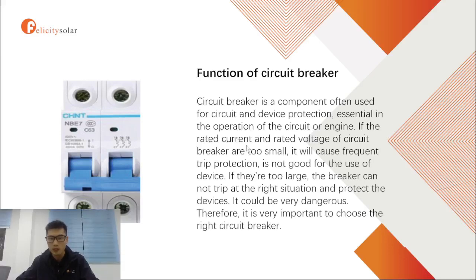If the rated current and the rated voltage of the circuit breaker are too small, it will cause frequent trips, and it's not good for the use of the device. And if they are too large, the breaker cannot trip at the right time and protect the devices. So it will be useless, and it could actually be very dangerous. Therefore, it's very important to choose the right circuit breaker.